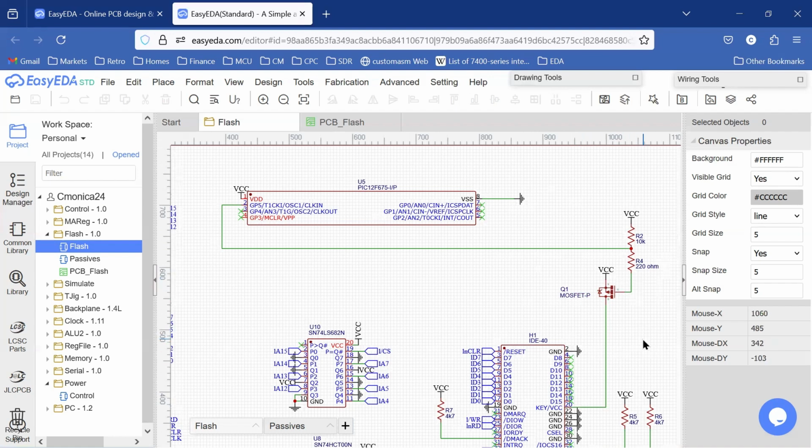So in operation then, when the power is applied to TTL Computer 2, the soft start power supply for 200 milliseconds is going to be something less than 4 volts. The PIC microcontroller will begin timing here, and at 500 milliseconds, so after the power supply switches to the full 5 volts, this will again bring the P-channel gate low and allow the MOSFET to drive power through to the compact flash card.